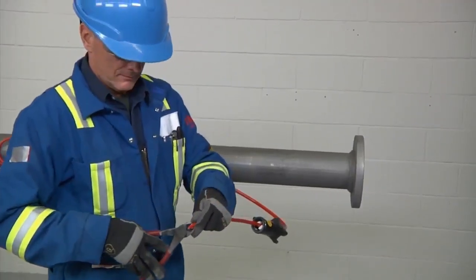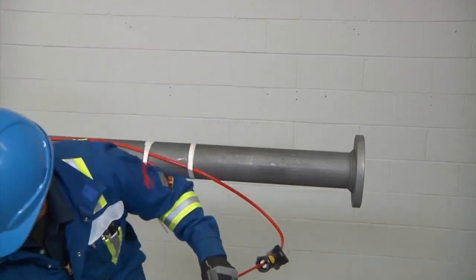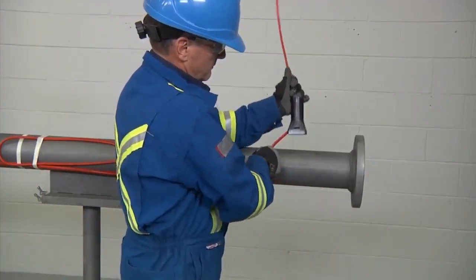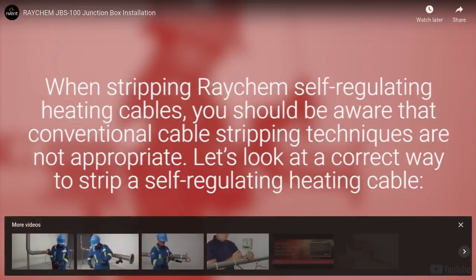Now, square off the cable end with a 90-degree cut, but do not attach to the pipe yet, and proceed to stripping the end of the cable. When stripping Raychem self-regulating heating cables, you should be aware that conventional cable stripping techniques are not appropriate. Let's look at a